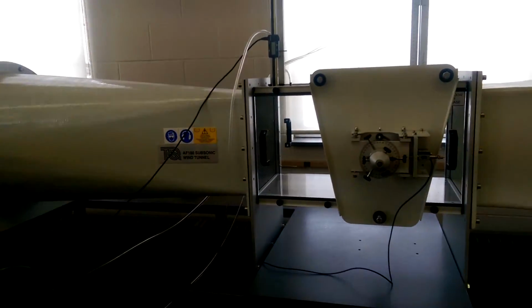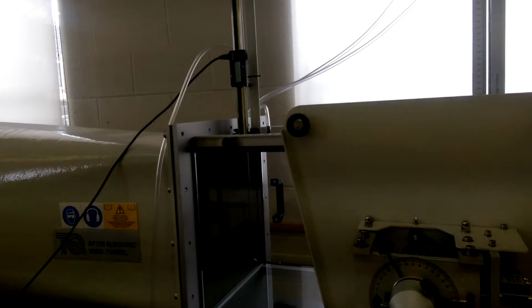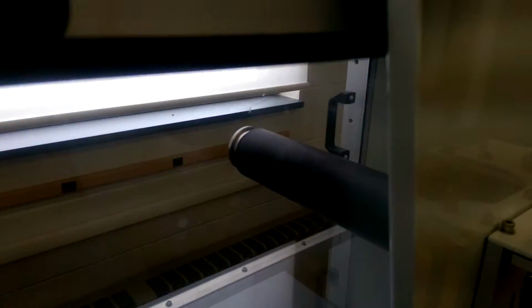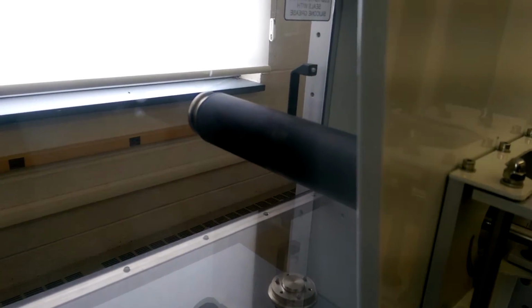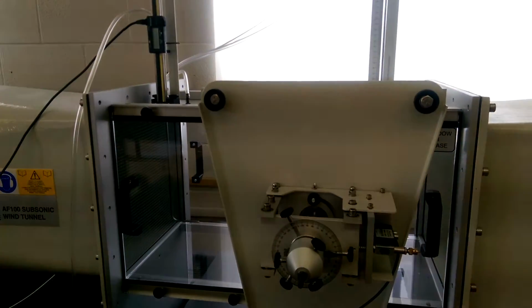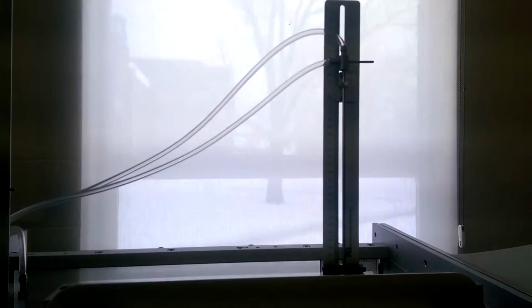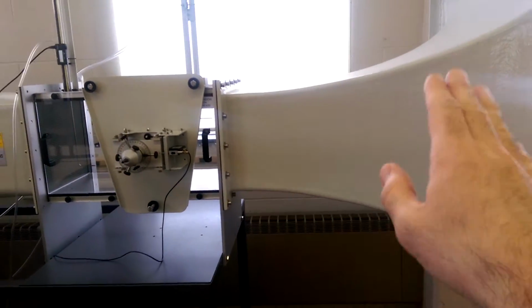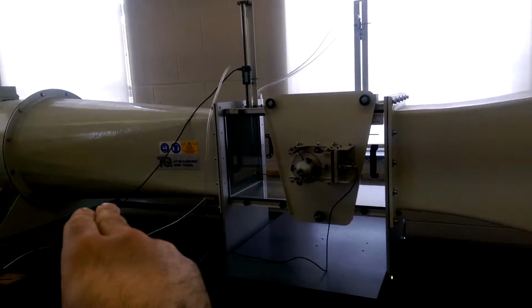This experiment is for the traverse wake test, which is basically looking at the pressure distribution behind a circular cylinder. In this experiment, there are two pitot tubes. One is a pitot-static tube, which is used to measure wind velocity. You can see in the test section of the wind tunnel the pitot tube facing against the flow of air. In the wind tunnel, the air is flowing from this side of the wind tunnel to this side.